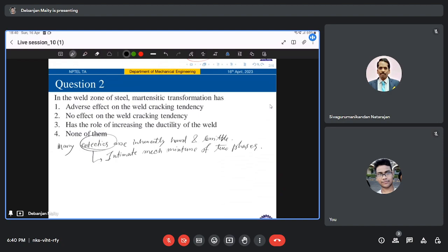And it should come as no surprise then that once extensive segregation of a eutectic constituent to grain boundaries occurs, the ductility of that solidification structure is lowered considerably, right? So this problem can be made worse by the fact that reducing this embrittling effect means removing or drastically altering the structure of the eutectic. So you have to do that. The only way to do this is by heat treatment, correct?